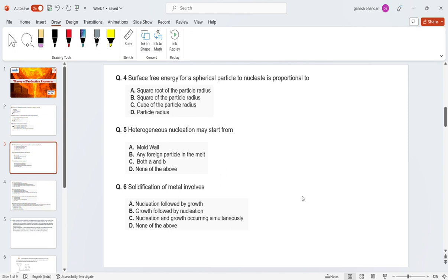Suppose I have two metallic chips, one of copper and one of brass, or simply two copper wires I want to join by soldering. By wettability I mean the forces between your soldering alloy and that copper wire. If it becomes more, then there will be more wettability, and it will spread more on that wire and join those two wires. I think I am clear. Or if you have any doubt, yeah.